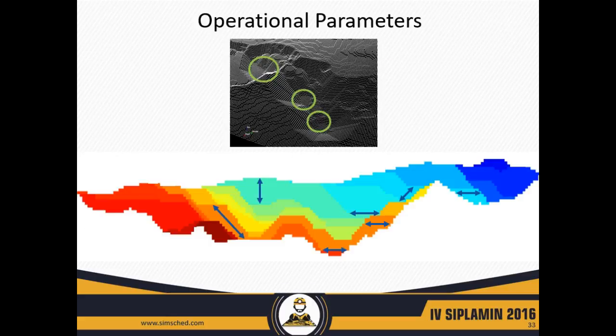Another point is we have the operational parameters like the bottom widths and the mining widths, that we respect using the surfaces. We have vertical advance rates, and all of this is respected during the optimization. It's done all at the same time, so the user can also play with those parameters and see, because once you change a constraint like that, the optimizer will look for the best solution, maximizing the net present value of the project, given that you have forced certain parameters.